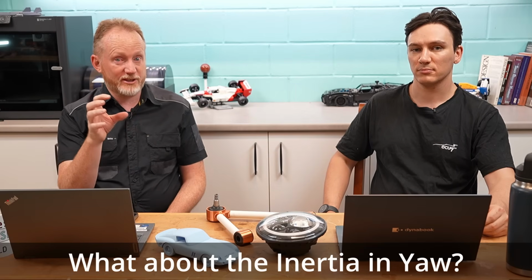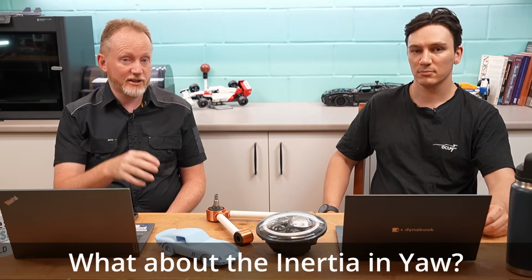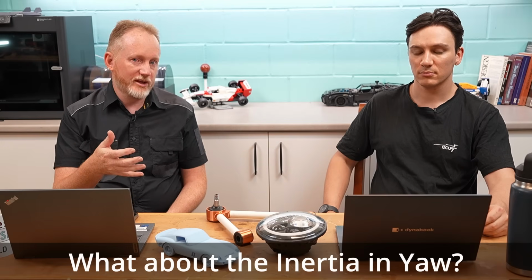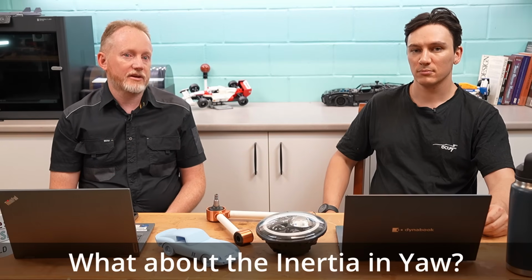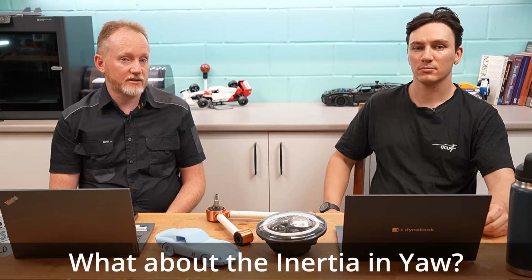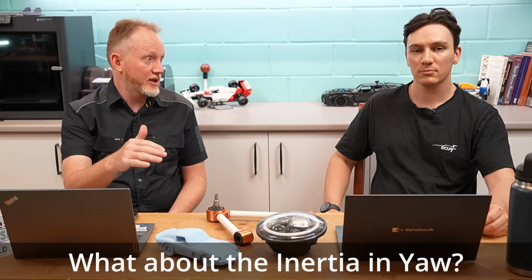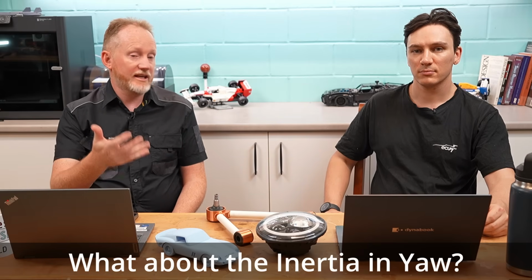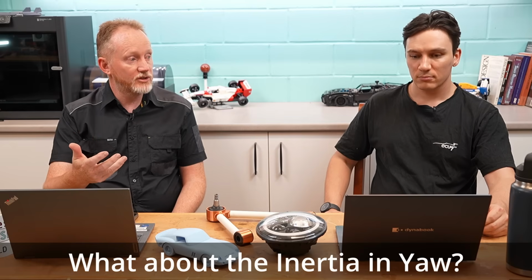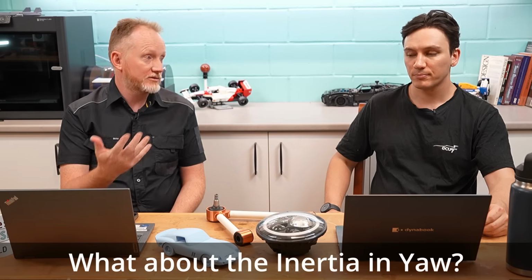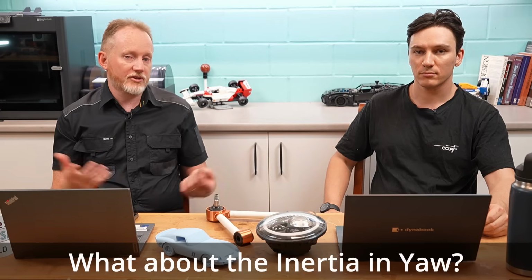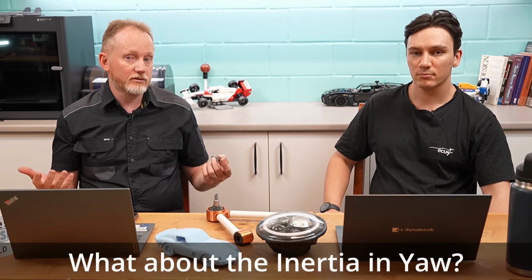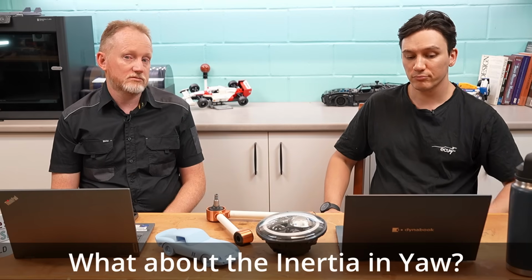If you're going to spend ages on your vehicle dynamics model, you can get it really quite accurate, but we're going to lack really good tyre data. I'm not going to put the effort into massive, complicated vehicle dynamics models for this project. I'm just trying to do the bare minimum to answer the questions we need. I'm looking forward to when you get out on track and do some spring damper tuning, have a play there, and maybe bring some aero stability in. But I think polar moment of inertia is really important. If you want something fun on the road, it's likely to be light and small.